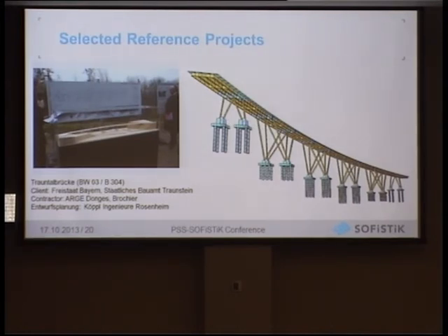So the approach was to have as slender a superstructure as possible in order to make it soft, to not generate too high forces. And you see that here, to have these V-shaped supports in order to have also a slender superstructure. So we have less supports, or half of the supports in the bottom than we have supported points on the superstructure. So this was done by also modeling because it's in a constant curvature, but we want to optimize; we supported the engineer for the tender design to optimize the steel quantities.